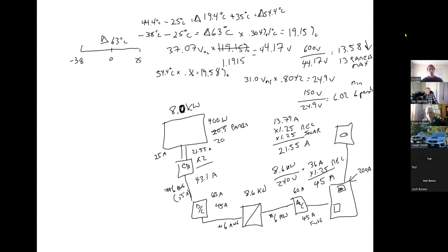but I've got a problem. If I try to put a 45 amp breaker with 200 amp service from the utility in a 200 amp panel, I've exceeded the 120% rule. It tells me I can only go to 120% of the bus bar rating of the service panel. So with a 200 amp service panel, 20% is going to be 40 amps. And I'm trying to put in a 45 amp breaker when I could only legally put in 40 amps.